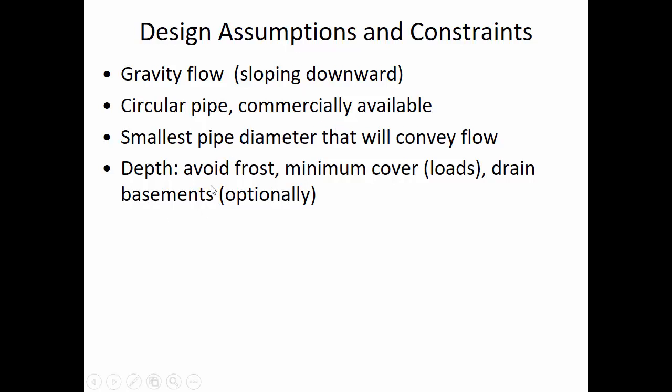Then there are also considerations having to do with how deeply the pipe can be buried, like making sure that you're below the frost line so that the water inside doesn't freeze, distributing the loads above it by achieving the minimum cover specified by the company that produces the pipe, and so on.